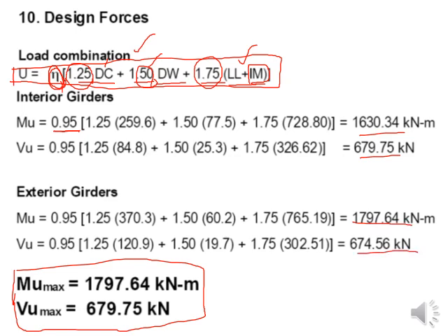Finally, out of these two, interior and exterior, if it is a plate girder bridge, where the two exteriors will be plate girders and the interior will be the stringers, I mean the smaller beams, hot rolled beams you can provide, and built-up, properly designed plate girders you are providing at the extremes as exterior girders. Then you can use these values separately.